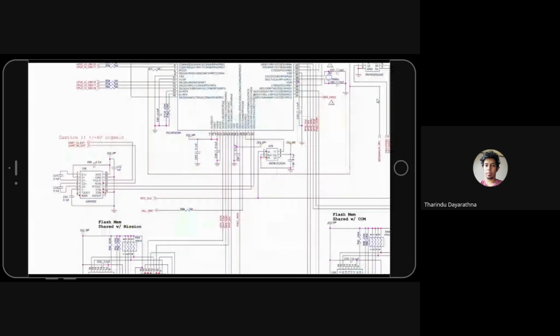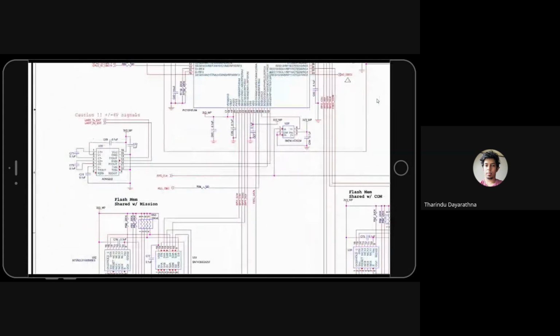You need to remember something here. Normally, UART is TTL in a PIC IC, so the voltage varies from 0 to 3.3 volts. But there's a problem in this path. In the initial design, this side is TTL. If you use a normal serial reader, you have to connect here to this line, the RX TX line. Maybe I'm not sure. Wait.